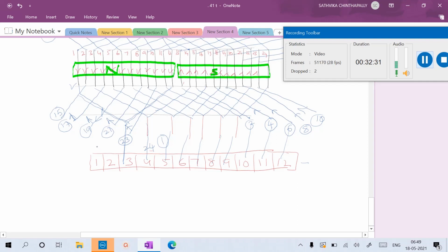So 21 is connected here, and 23 is connected to the slot and 21 is connected to this one. Now this connection: here slot 1 is connected to conductor 21, you can see here, and commutator segment 2 is connected to 23. Then 3 is connected to conductor 1, and 4 is connected to conductor 3. Similarly you connect this one. Simply don't confuse, just connect it.